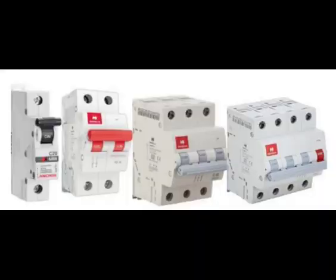Type wise, if we generally think about MCB, it has 4 general types. We can see over here that it is single pole, dual pole, 3 pole and 4 pole. According to our application, for single phase we can go for single pole or dual pole. Likewise, for 3 phase applications, we can go for 3 pole or 4 pole MCB. We are not going into detailed specifications like B type, C type, D type, K type, Z type here. We will discuss all these things later.